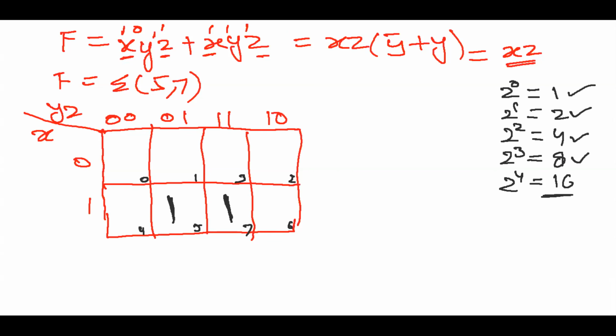Always look first at the maximum group that can combine the maximum number of ones. This is our prime aim, to have a larger group. Now, if you see the entries, how many ones are there? Only 2, right? So what could the maximum group be? Can we make a group of 4?